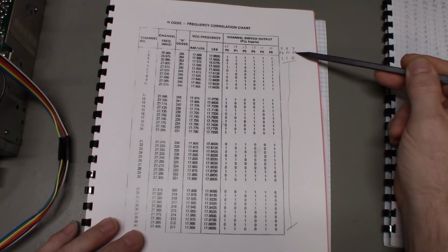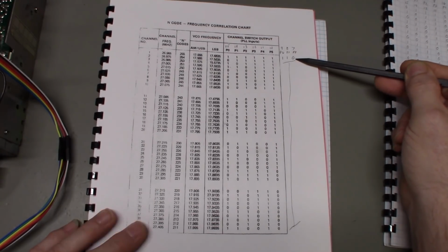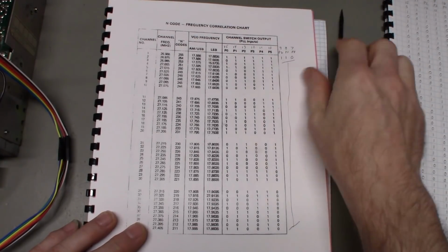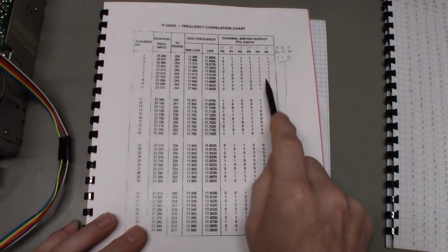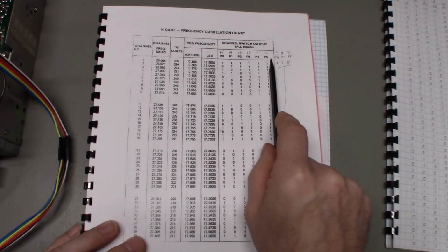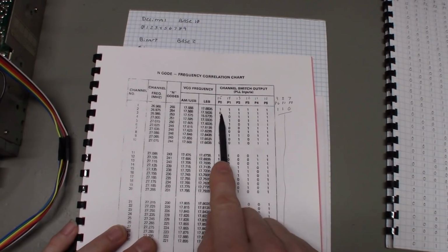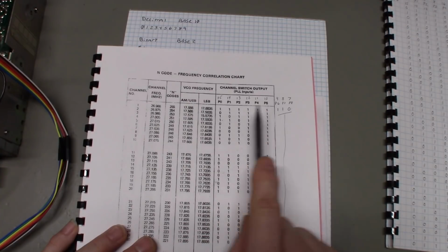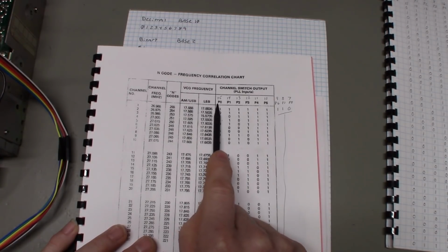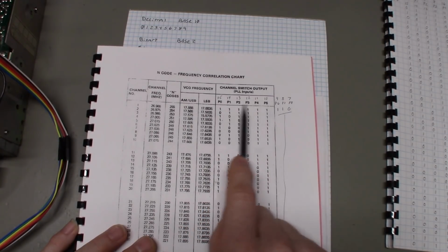Pin number 7, which is programmable pin number 8, is always a 0. It's always at ground potential for all 40 channels. So they didn't even bother to write them in the book. These are the pins that change. Depending on what channel you're on, all of these pins will change state at some point in time. But like I say, the problem is the code is written backwards here. I think they did it because they're using what I call the identifier P0, P1, P2, P3. They did those in increasing value. They shouldn't have written it like this.